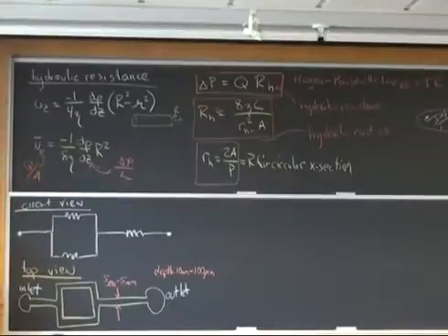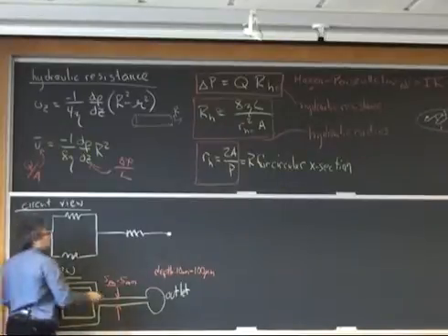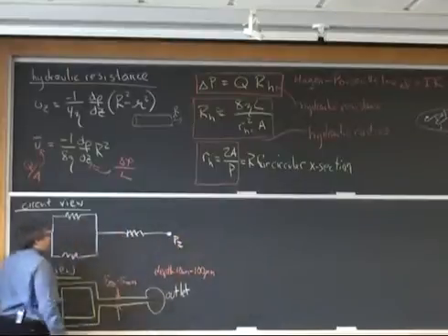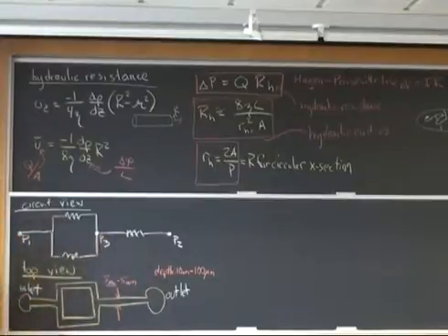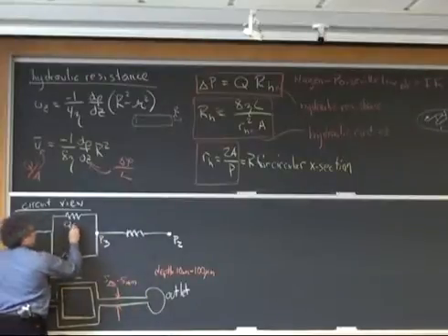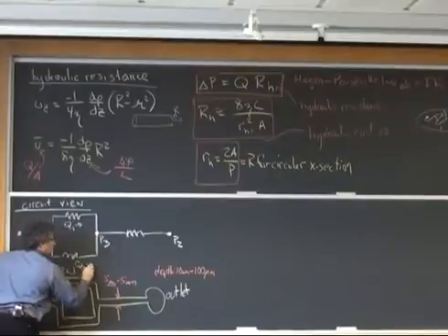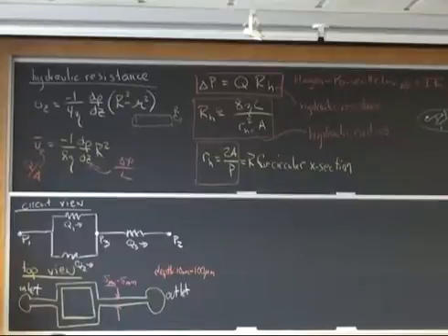That is completely analogous to having an electrical circuit and applying a voltage at one inlet and having the other outlet connected to ground. So we can think of this system then as having some pressure at the inlet, some pressure at the outlet. There's a node here where these connect, and I can give that a pressure as well. I can say really that there are 3 different tubes that I want to consider. And so I can say that they each have flow rates.